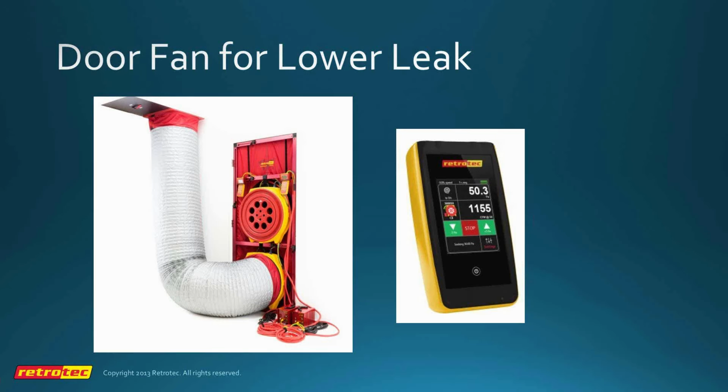One development that we've had when we came out with this gauge, which is the DM2, is it has a set to zero function. So we can set this fan to our test pressure, which would be 10 or 50 pascals, and then we set the other fan, this one down here, to zero, so that the pressure across the ceiling is zero. As the fans are running, they'll jockey back and forth until they come into balance. The old way was that we would lift up a ceiling tile and put smoke there and see if the smoke went up or down.